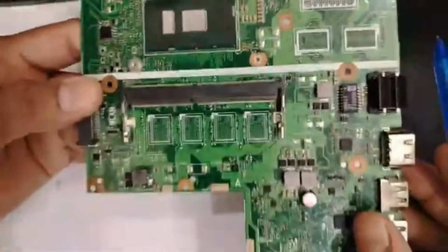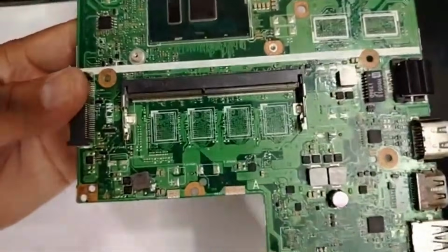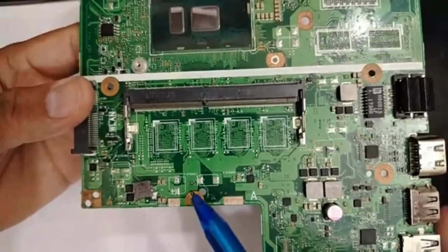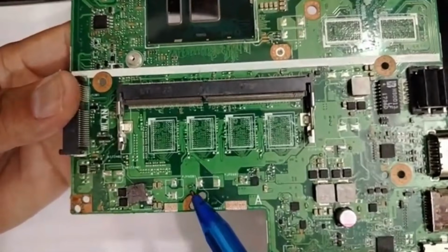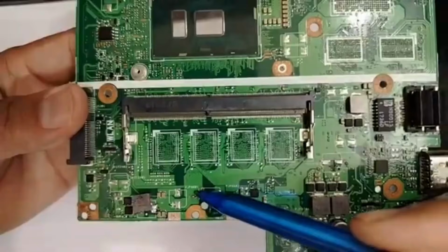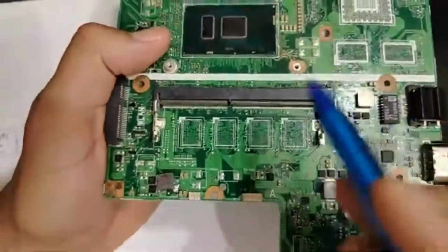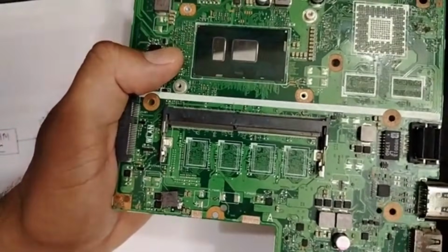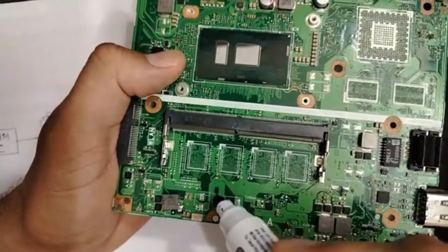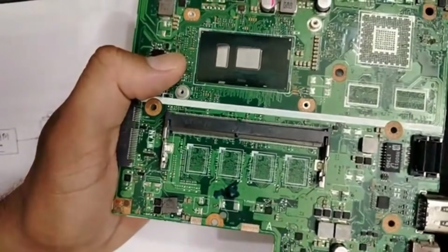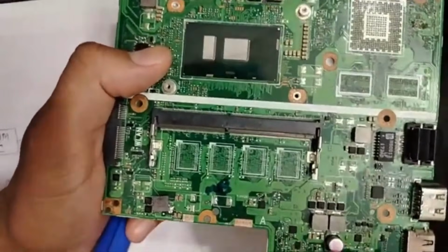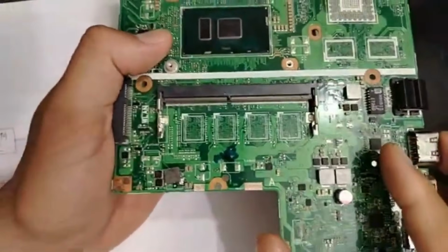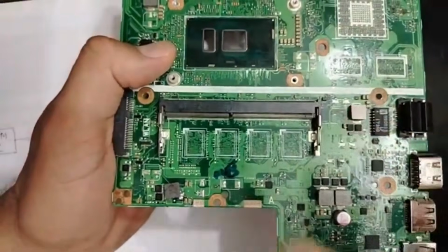This one means if we have a short in this side, we have to remove this pad. This pad, we have to remove it in order to separate the motherboard. Here, guys, I will call it MP. This point here, this side is the motherboard, MB. Okay, here we have the motherboard, guys. So to make things easier, I should separate these two parts.